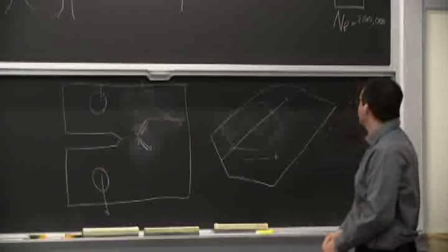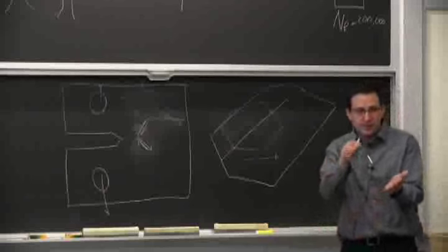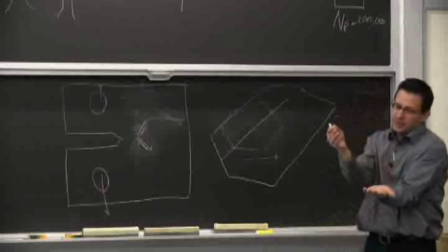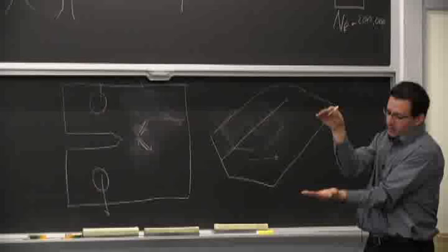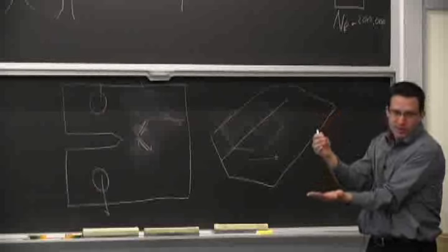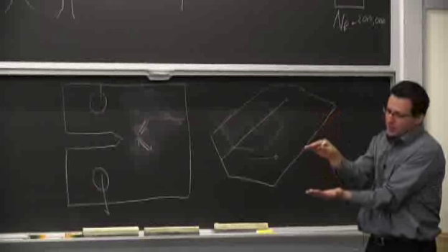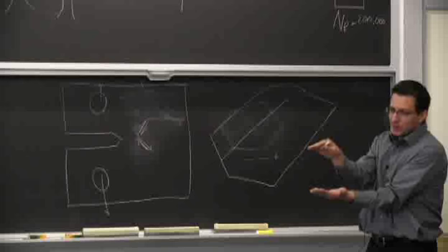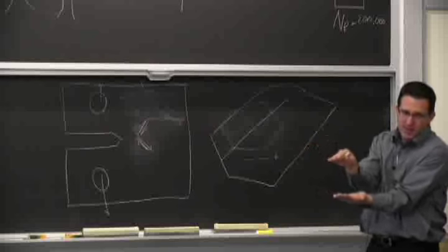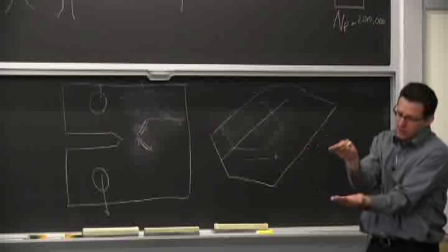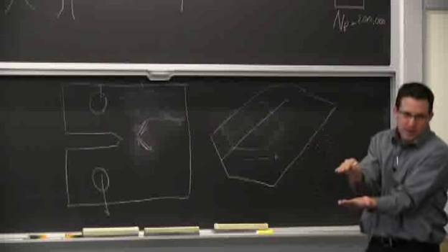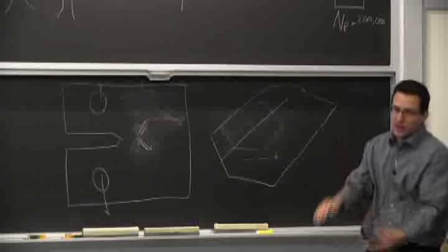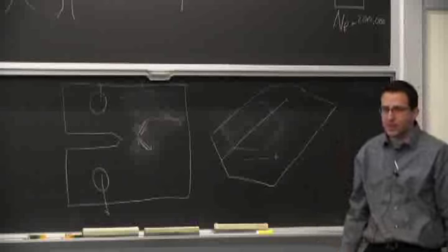So you're reducing the variation of stress level at the crack tip. The extreme limit is I open the crack, I bridge it, and I remove the load, and then now I apply the same load again. Nothing happens. There's no fatigue anymore. So it's the same idea, except that it's maybe going back down half the way. It crushes on the opposite fracture, and then it does go back up again. It happens a lot, and